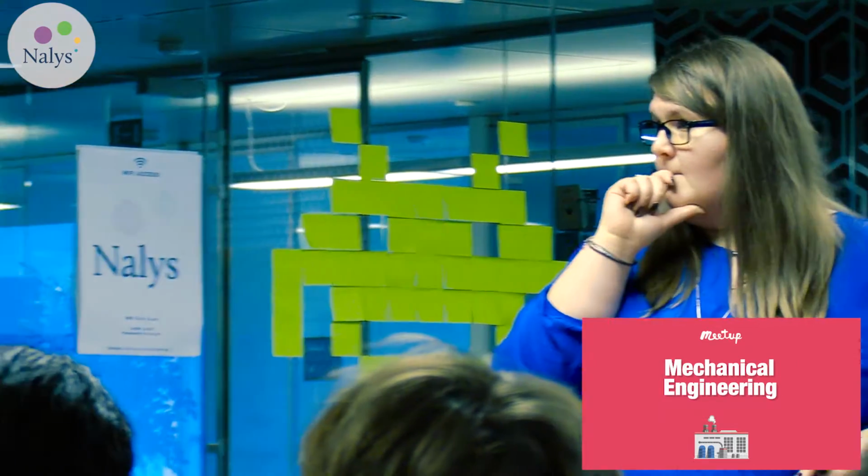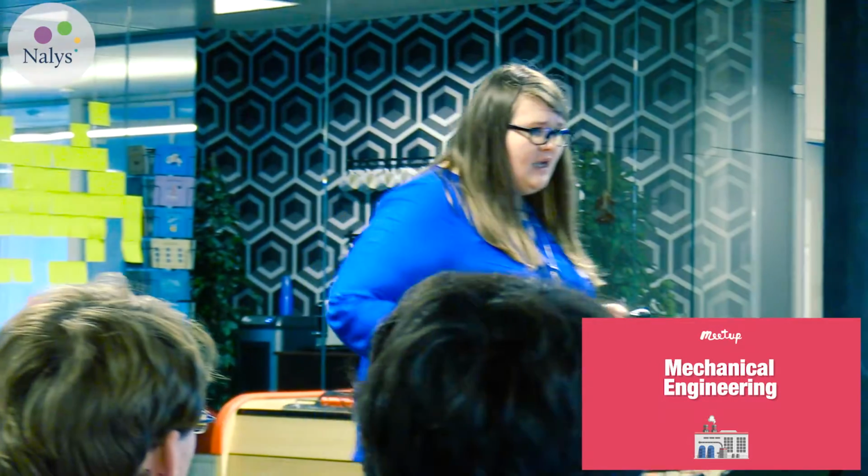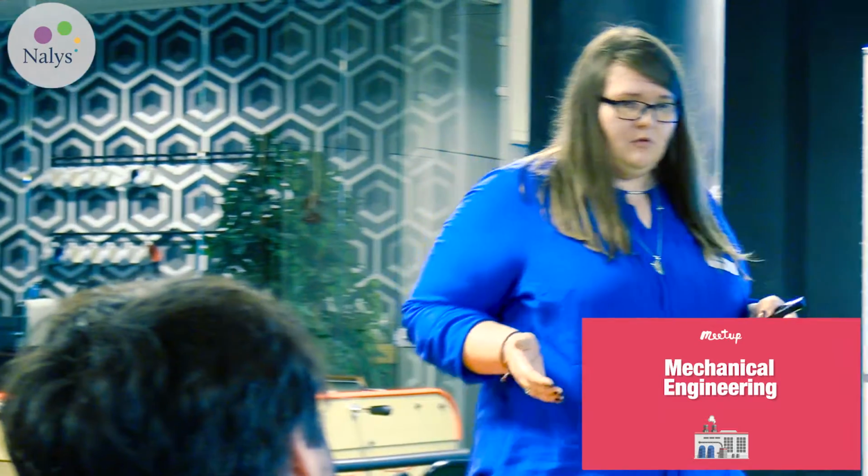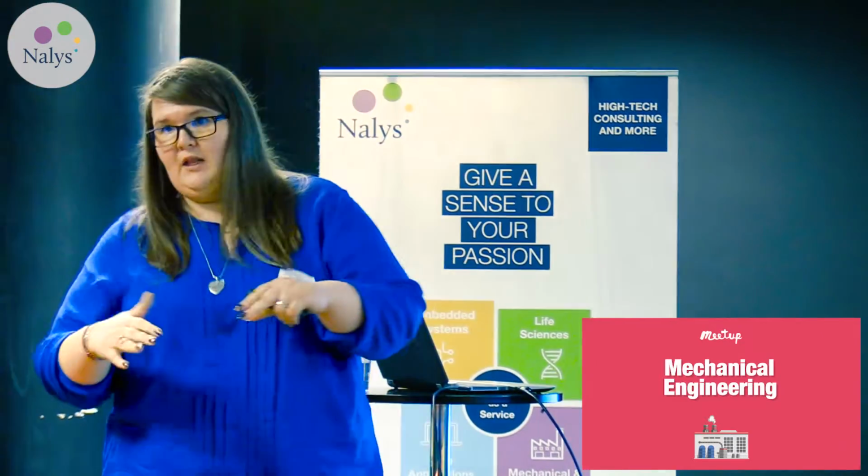That's what he said with the scale. Another thing that's very important, you have to work in clean rooms. Yes, so the environment is also different. And you need molds, mandatory, and the complexity of the molds matters. I remember at university we had a training like this. You can do sandwich structures. That means a laminate. You put some glue, then the honeycomb, then some glue, and then the laminate.